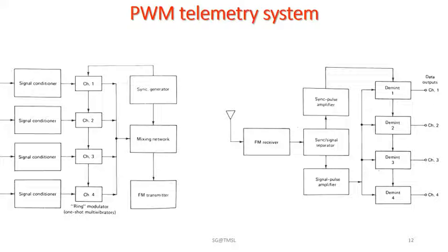And here the width of the square wave output of the first flip-flop is the same as the width of the first signal pulse. Now the second flip-flop is turned on when the first flip-flop is off, and is turned off by the subsequent signal pulses, and so on. It goes down this line one by one.